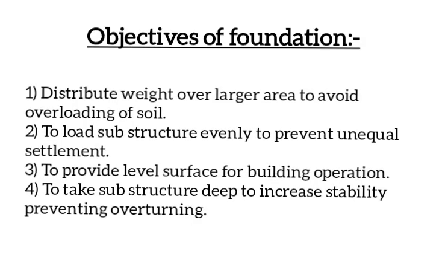The objectives of foundations are to distribute load over larger area to avoid overloading of soil. These foundations are so distributed that they prevent unequal settlement of structure. Foundation gives a level surface for building operation. It increases the stability of structure and prevents overturning.